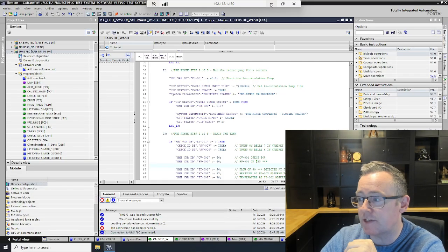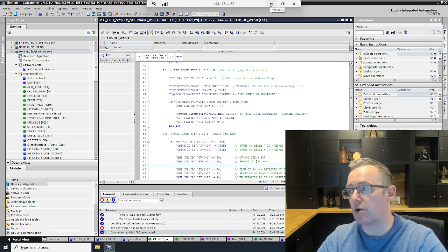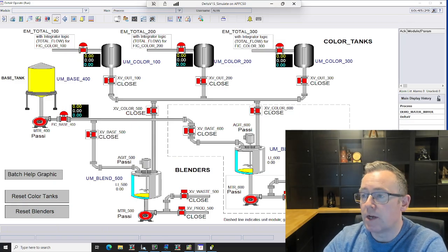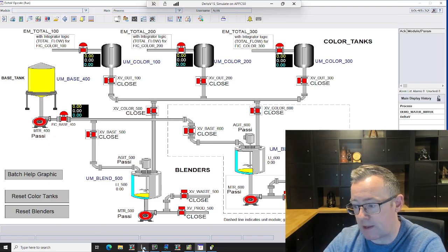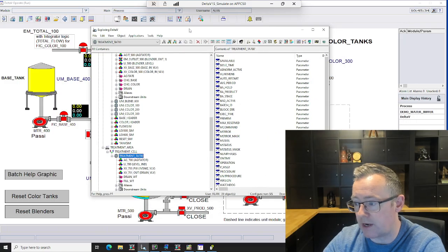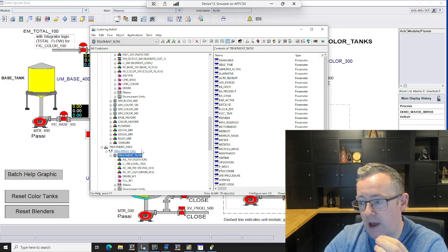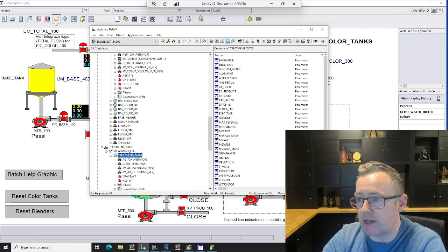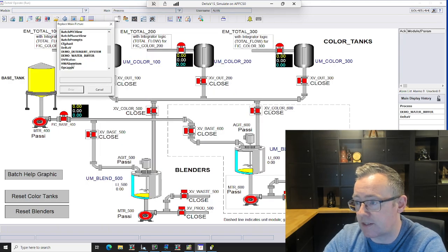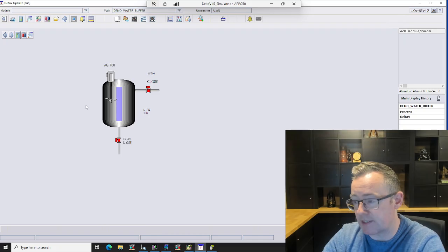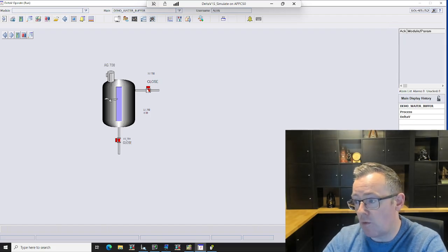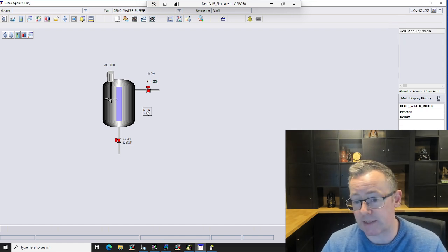And essentially, DeltaV does work with structured text, but it breaks it out in a highly modular way. So for the very start with people, what I have basically done is I've created this area called the water buffer treatment area. Essentially, I have created a highly simplified system where it's literally just one tank, an open valve, and a closed valve. And then we have a level sensor in the middle.